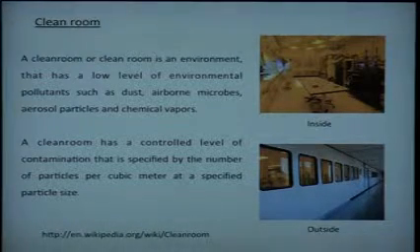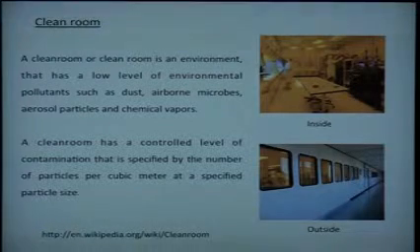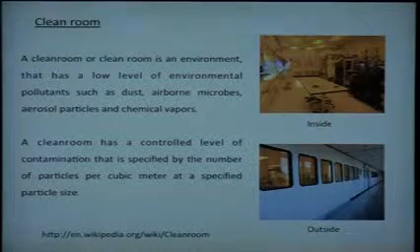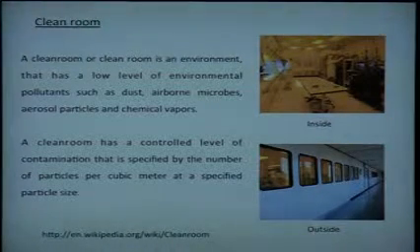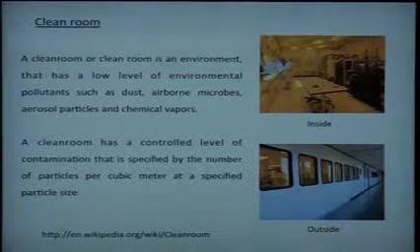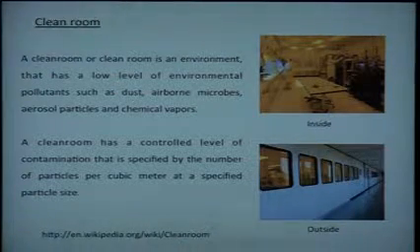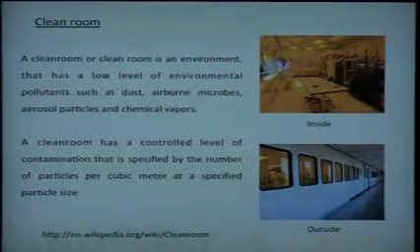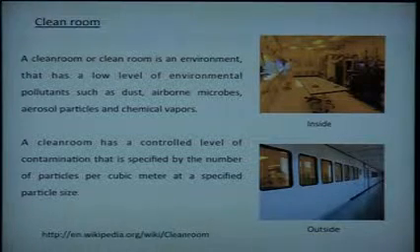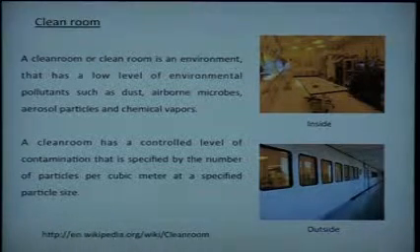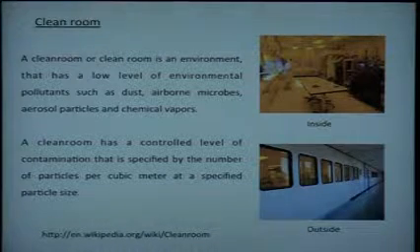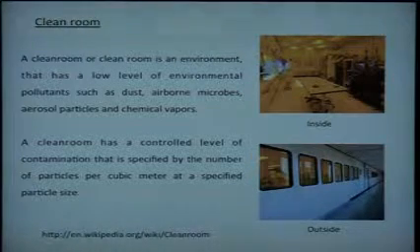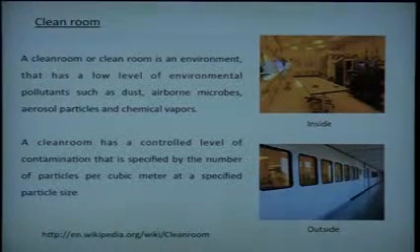And here even the floor would be made in such a way that it won't attract dust, right? Dust is attracted whenever you have a surface which is carrying charges. So dust tends to settle down on surfaces, not just by gravity, because more often they are Brownian particles, but they settle on surfaces which are carrying surface charge. So if you can drive away the surface charge, dust will not be there. I mean, at least it can be avoided. That's why the flooring is made up of electrostatic layers which conduct away the electricity. There is nothing like stored charge on top.